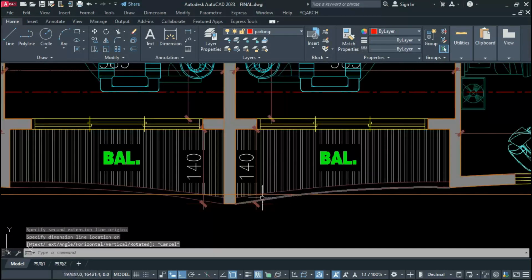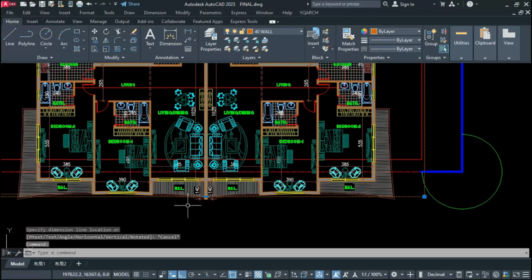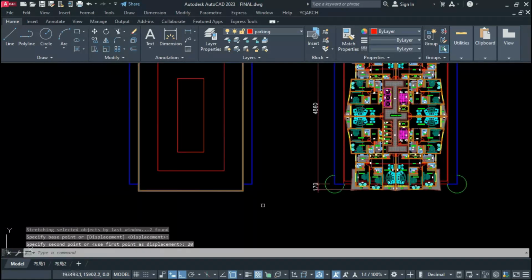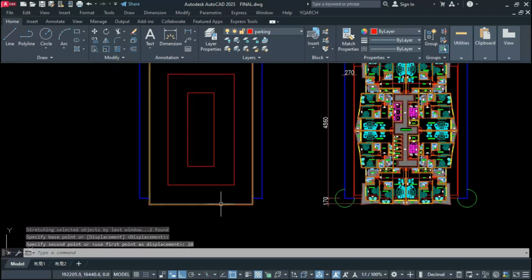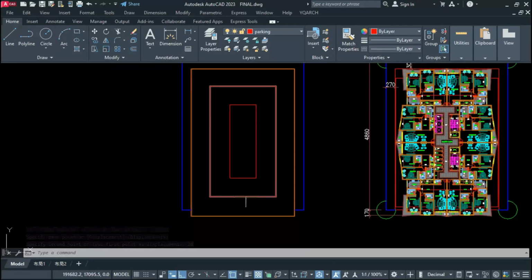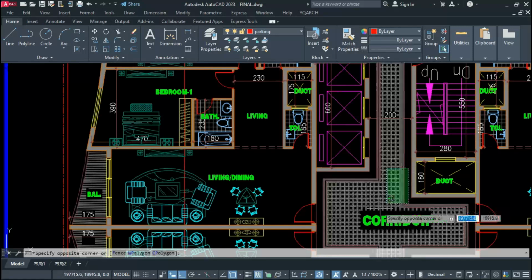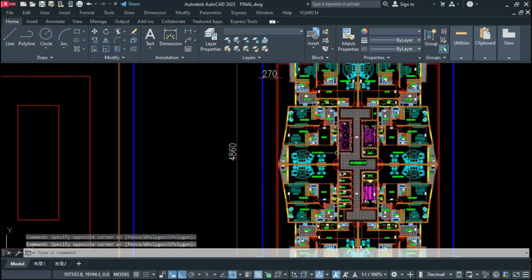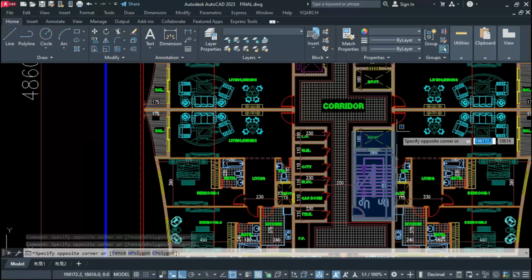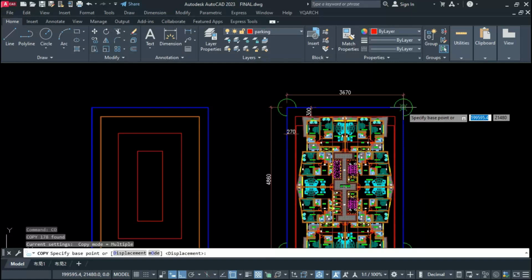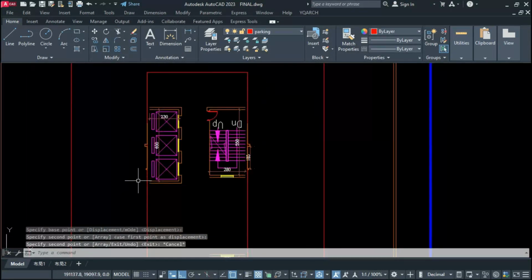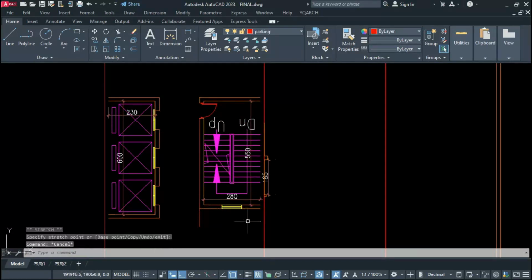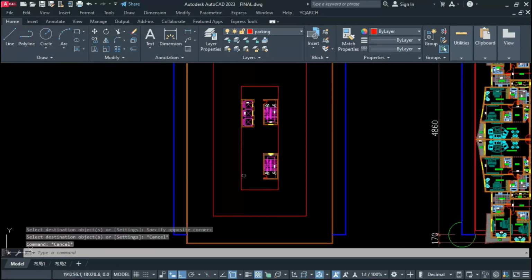So we will cover this thing very carefully, okay, when we finalize one time. For now, we'll keep this 17.20 centimeter out, okay. For this reference, we have taken approximately 20 centimeter more, okay. What you have to do, just let the shear wall, because this will cover our shear wall, okay, and let this here also. This will go from ground floor to top floor, okay, and we'll keep here and provide wall lines and provide shear wall lines properly. Now we are getting something like this, okay.